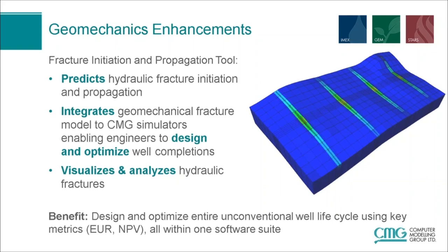We can also import microseismic data and SRV data for defining complex hydraulic fracture networks. And third, if you've modeled your hydraulic fractures, whether they're planar or complex networks, in third-party software, and you want to import that into our flow simulator to do some history matching or some forecasting, we also allow and assist with the importing of that third-party hydraulic fracture definition into our flow simulator.